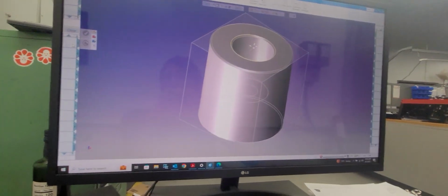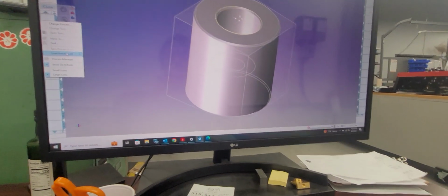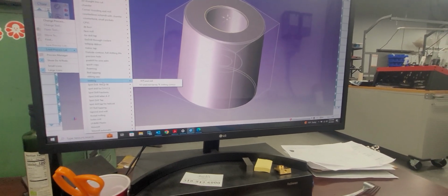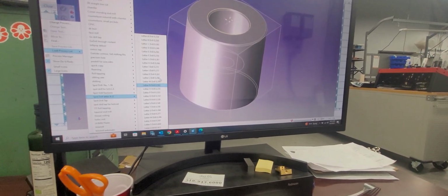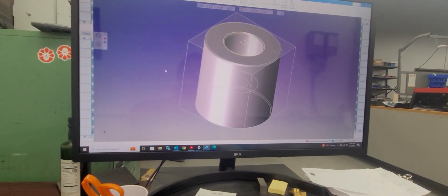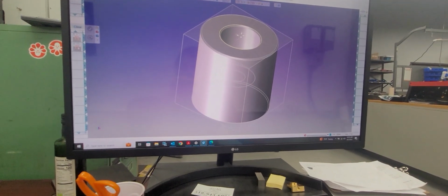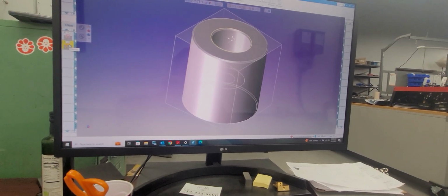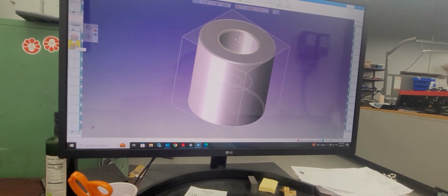So you're over here now in Gibbs CAM. Not the most powerful, but certainly very user-friendly and efficient. So look, let's go for that 0.257. We'll go in here, we'll go for the letter F. This is all being pre-populated. There's that T131. So that bit there, pulling the macro, stops the mistake.